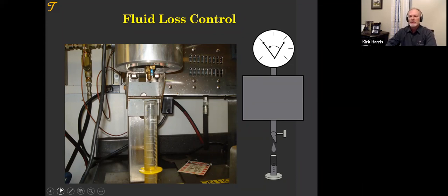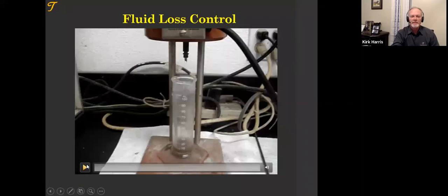On the bottom, where we're pressuring out, is a screen. Actually, we have the screen on top as well, but it is a 325 mesh screen. It's got pore openings, I think around 45 microns, but it is a very highly permeable screen that we try to push the cement through. The cement cannot go through and the water presses out of it as we apply 1,000 PSI of nitrogen pressure. And so here we're doing that. We're watching the filtrate come out.